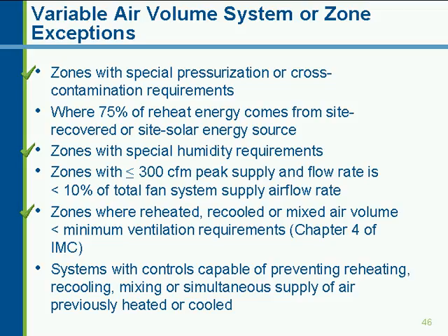But my general interpretation, or where I've seen this used, is places like museums, archives, places where archives are stored, possibly some areas of hospitals or laboratories where special humidity ranges need to be kept in place. I think if you can make the case that you need to keep your humidity in the zone within a narrow band, that this exception would come into play. But those are the types of applications where I generally see this exception being used.